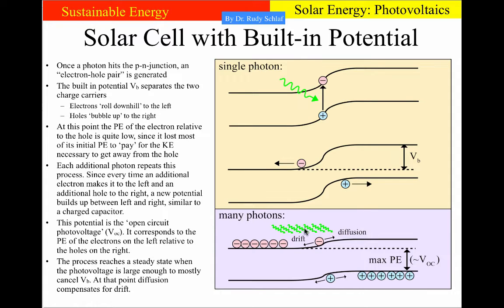So if we put on the solar cell many photons, then of course we get many electron-hole pairs, and more electrons will drift over to the n-type side and more holes will drift onto the p-type side. And you can imagine the more holes and electrons we get, the original built-in voltage, this potential here, is being reduced, right? Because formerly we had positive charges here and negative charges here, but now they're compensated with these photon-generated electrons and holes. And so that means that the voltage that is on the solar cell increases, and that's what you would expect: more light, more voltage.